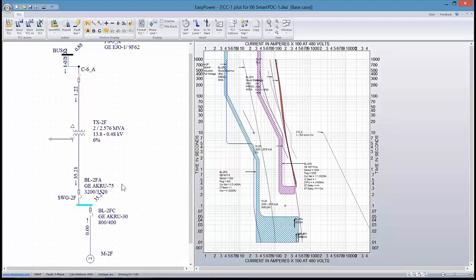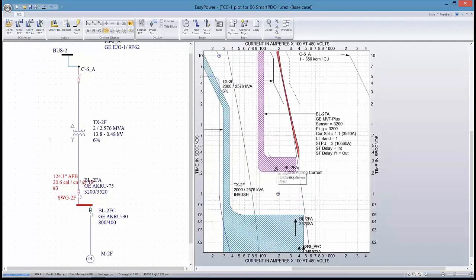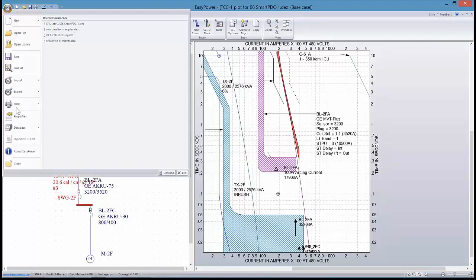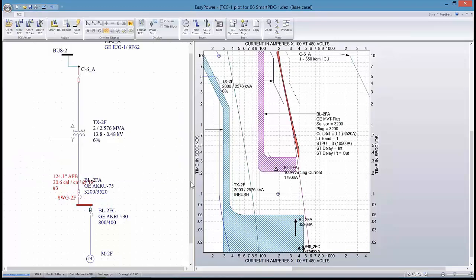And as we're calculating incident energy, you can see that it basically goes through the roof. So as I adjust this back so that my 100% arc current is used for the calculations, it becomes a much more reasonable number. And we'll see this in the, all right, the point I'm trying to make is a correlation now between this 100% calculation and what we're seeing in the arc flash incident energy.